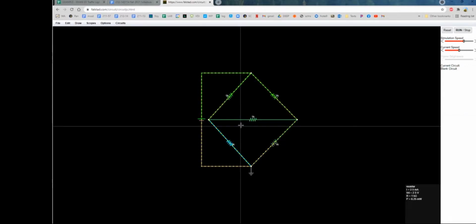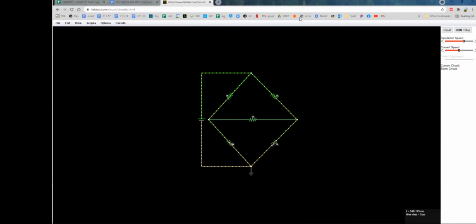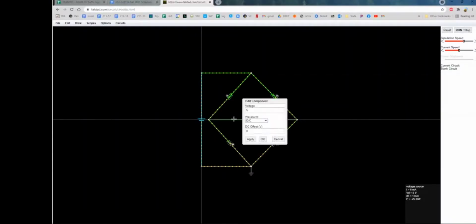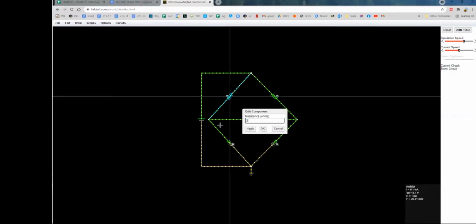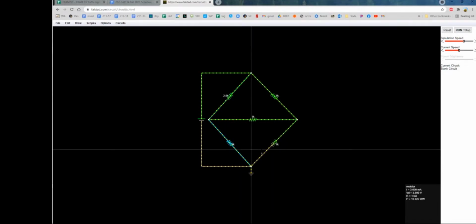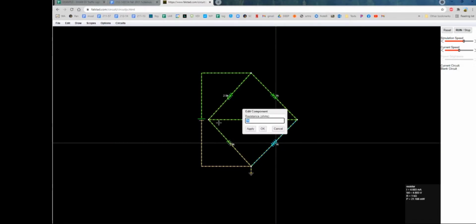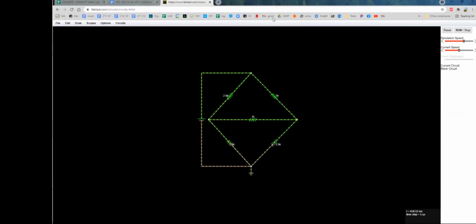All right, so now we just have to do the values. The battery voltage was 10.2. So let's go 10.2 for the battery voltage. 10.2, done. All right, top left resistor and bottom right resistor. So top left resistor and bottom right resistor is R2, that's 2520. So top left is 2520. Bottom right is 2520. Those are matched in this case.